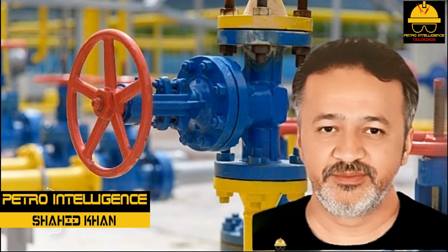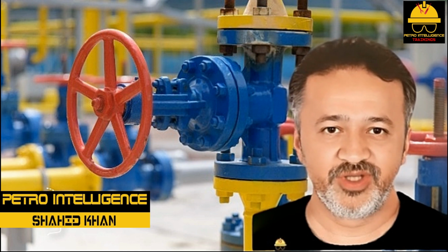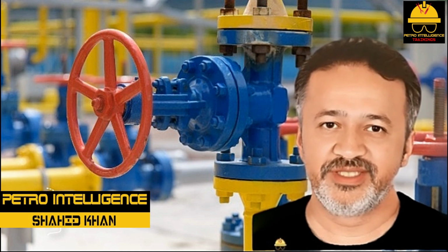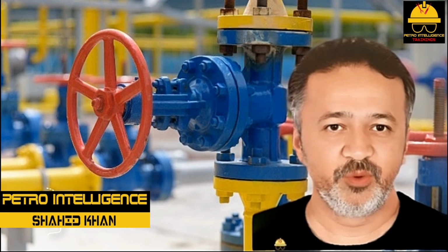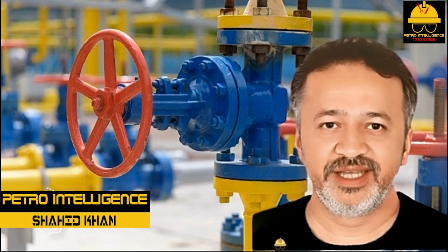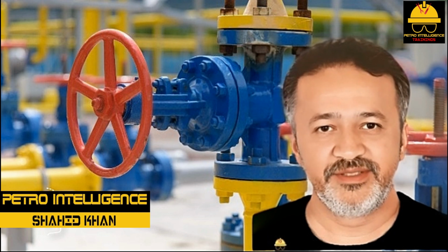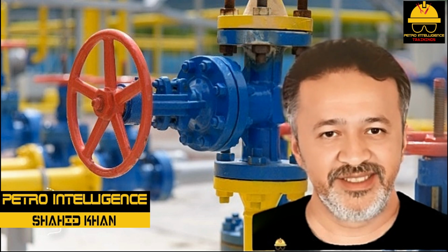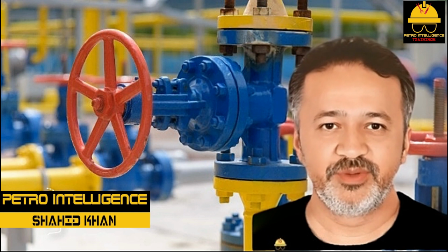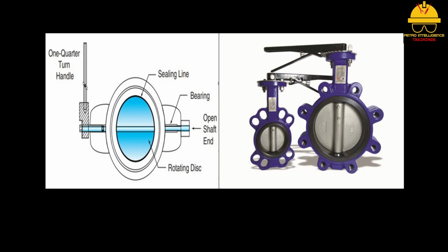Butterfly valves. Butterfly valves are commonly used for throttling and on-off service. The body of this type of valve is relatively small when compared with other valves and, therefore, occupies much less space in a pipeline. The flow control element resembles a disc. A metal shaft extends through the center of the disc and allows it to rotate 1/4 turn as shown in picture. A 1/4 turn is all it takes to fully open or close the valve.